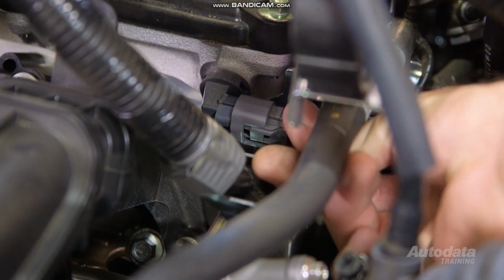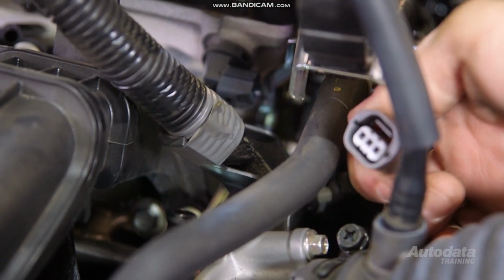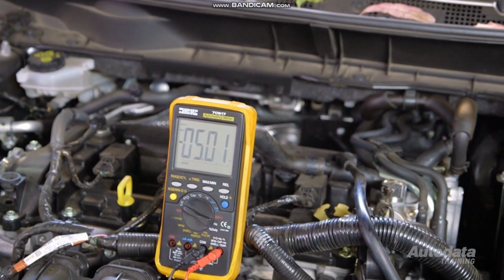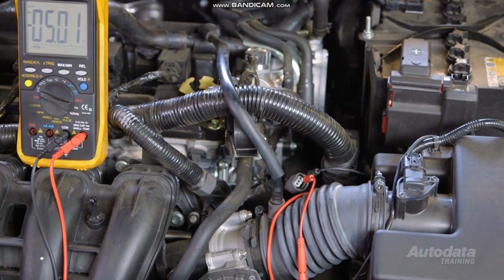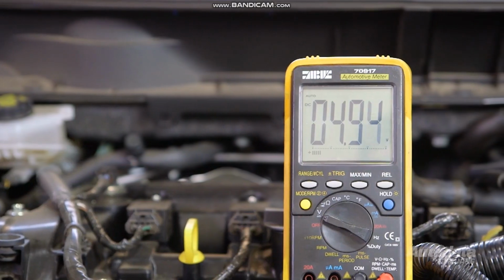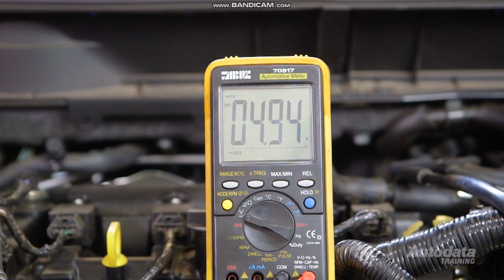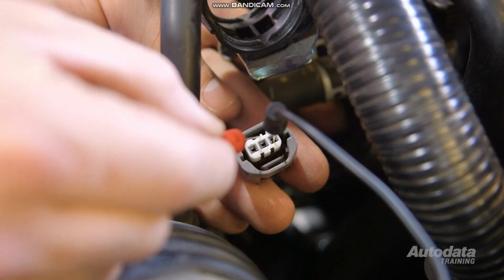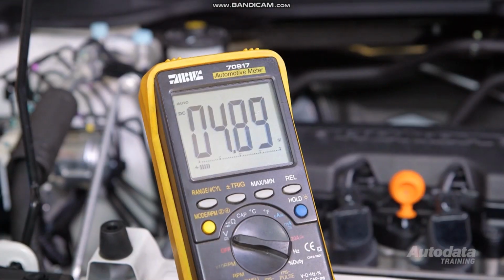To test the camshaft position circuit, turn the ignition off and disconnect the sensor that has logged the fault. Set the digital multimeter to volts, then place the red lead on the high reference terminal and the black to the low reference. Turn the ignition back on. The meter should display between 4.8 and 5.2 volts. Since this is a pull-up circuit, now move the red lead to the signal terminal. 5 volts should be displayed.